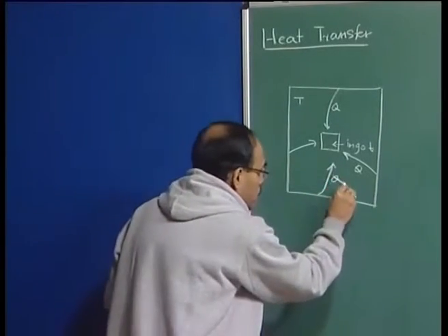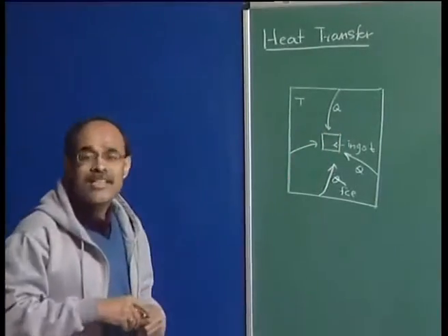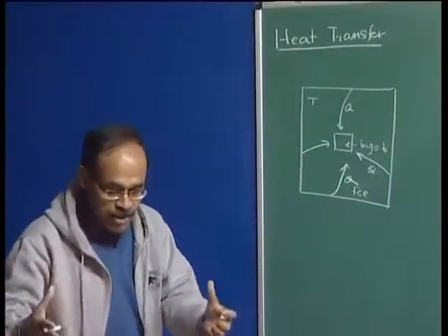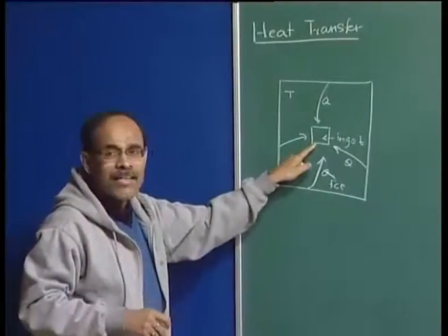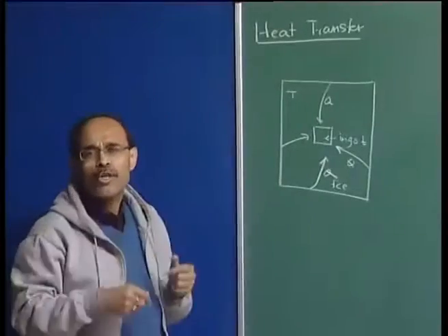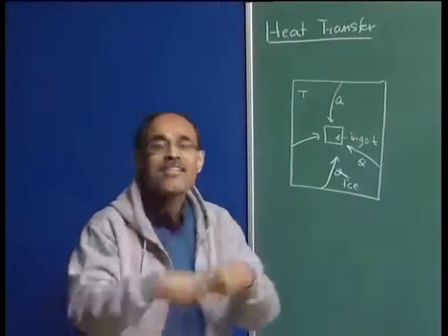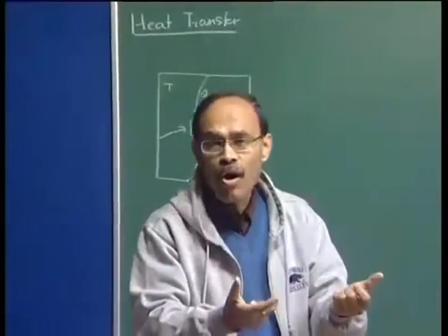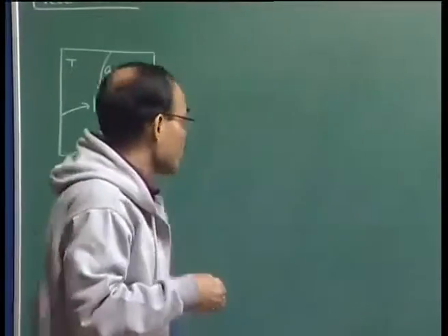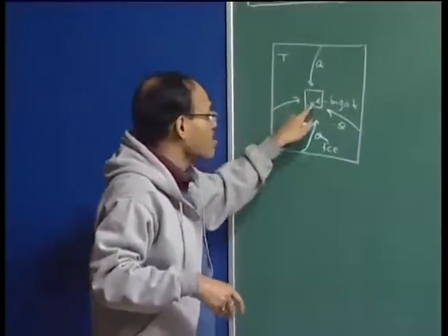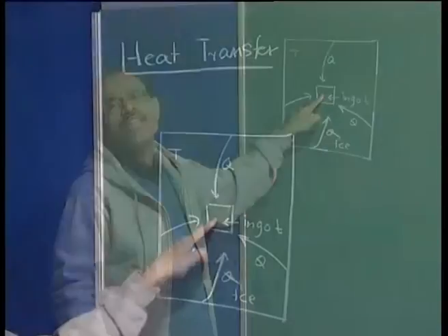Now, suppose I want to predict the homogenization time. I place an ingot within the furnace, and I want to find out at what time the ingot has become completely homogeneous, and only then am I going to take the ingot out of the furnace and subject it either to soaking pits, where the same temperature is maintained, or straightaway take it to the rolling mill. So, prediction of complete homogenization time or a uniform rolling temperature in the reheat furnace is of key interest.